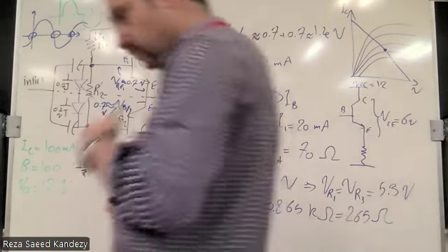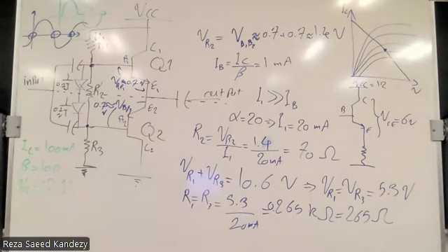For the capacitors, it doesn't matter in your case. But if you want to know how to design it, it depends on the frequency of the signal that you want to inject. What this capacitor basically does is act like a low pass filter.